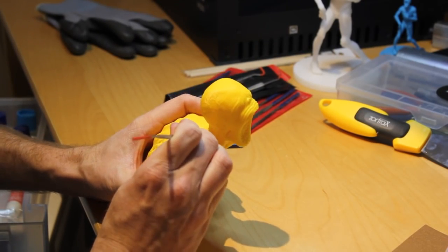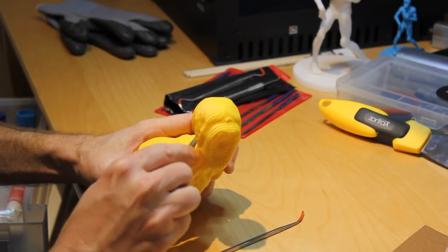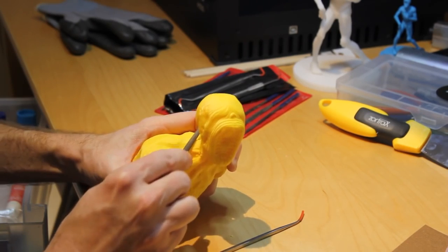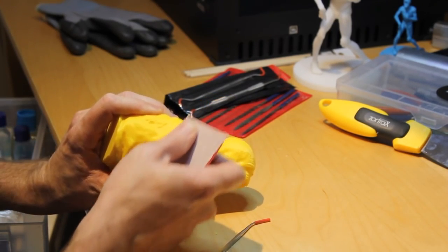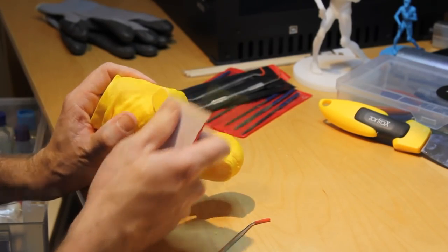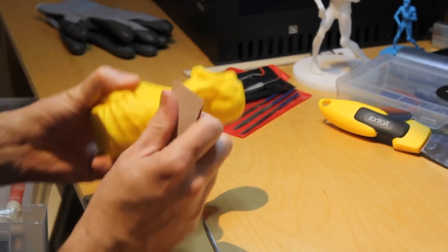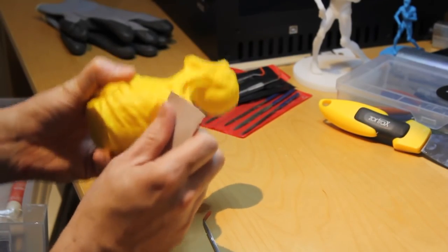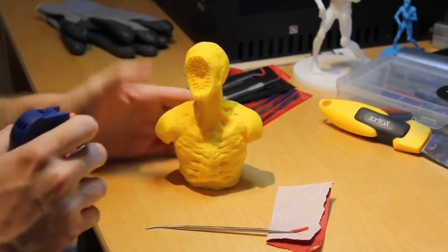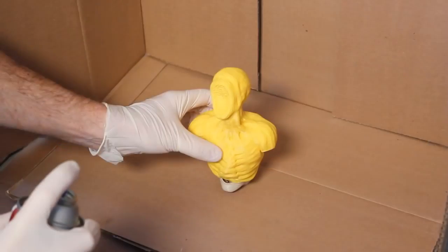So here we're getting into some of this hand finishing, and I'm just simply using a pick tool, a simple file, and there were just a couple little tiny areas where I might have had a little bit of support material remaining. And I'm getting a little picky here. I'm using some sandpaper just to file down some edges where I booleaned the arms where there might have been a little bit too sharp along the edges, so I'm just smoothing those out. And then I'm blasting off, making sure I got rid of all the dust before I get into painting them.